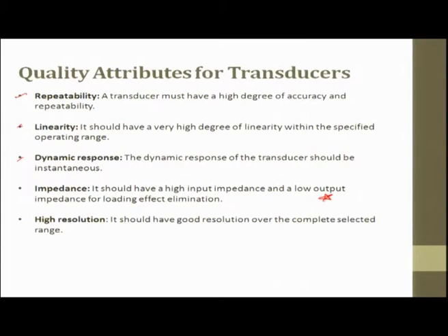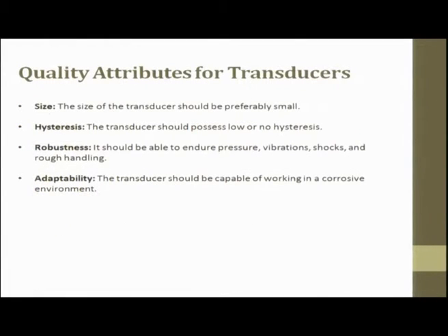This part is also very important. It should have very high input impedance and low output impedance such that it does not take the loading effect. Then high resolution is required so that it gives very close accuracy, and then size: the transducer size should be as small as possible. Hysteresis: it should possess low or no hysteresis.